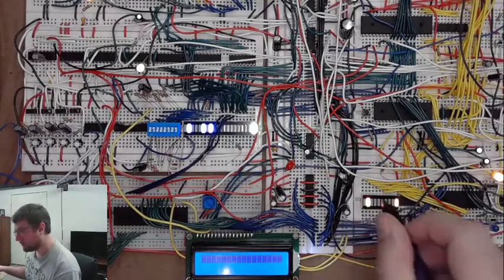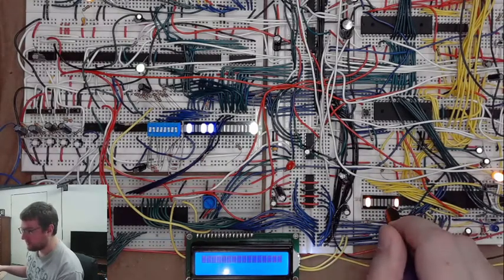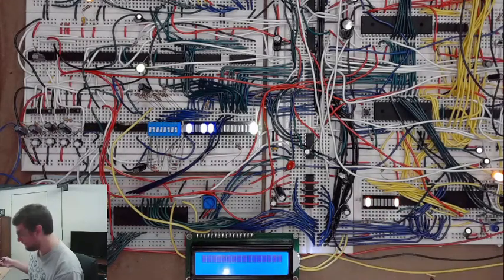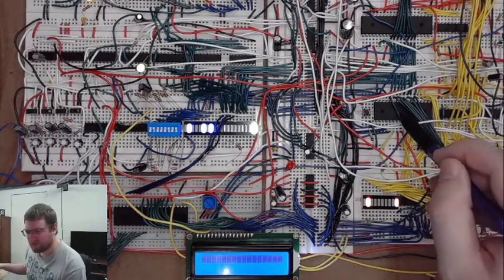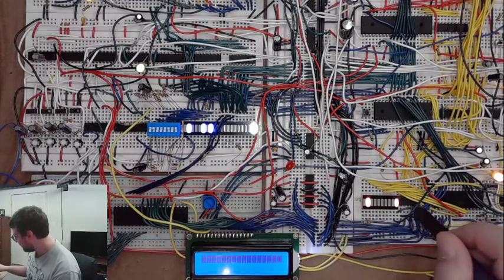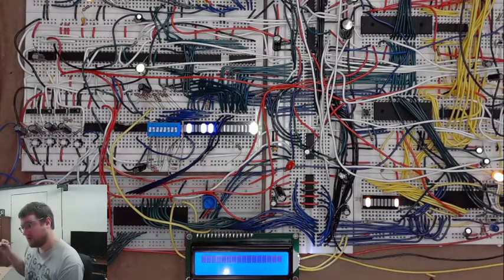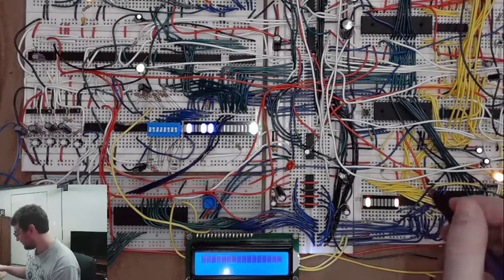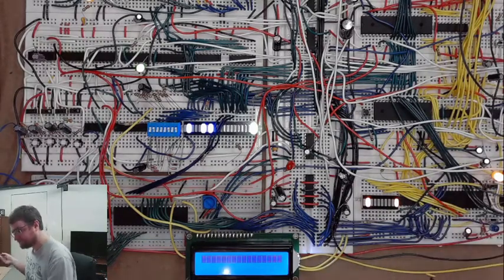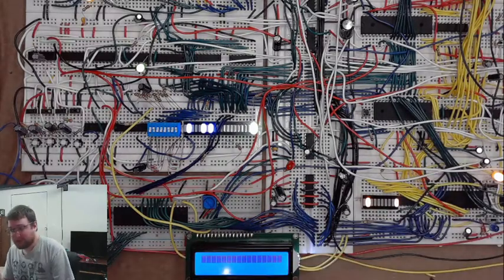we should be fine. Because this is probably my most sensitive device as far as getting write timings correct, and it works fine. The RAM, I think, is slightly less sensitive because it was even working when I wasn't doing it correctly, and the ROM as well, it was about the same. But yeah, some of my most sensitive devices are the D latches. Yes, D latches. They aren't synchronous, and you have to make sure that your data is still there when you pull the enable. And it's just working. So if it ends up not working at some point, we'll worry about that when we come to it. Enough talking.